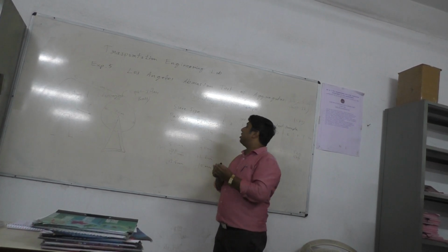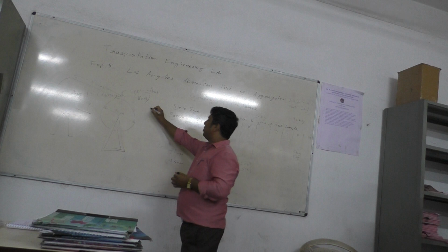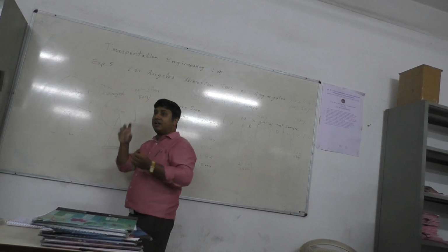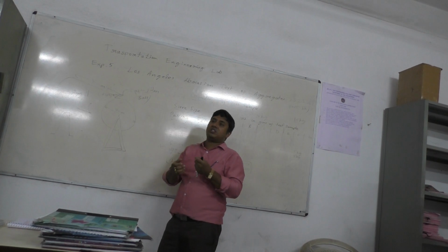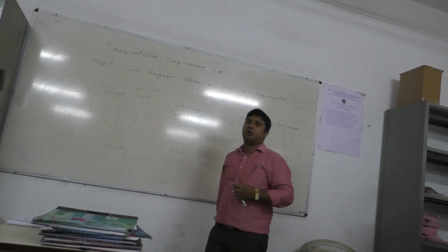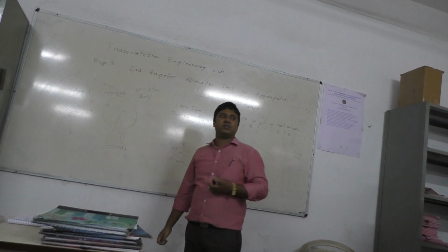And we will take the 1.7 mm size sieve, and then we have to check how much is passing. Passing divided by initial into 100 is your percentage of abrasion.